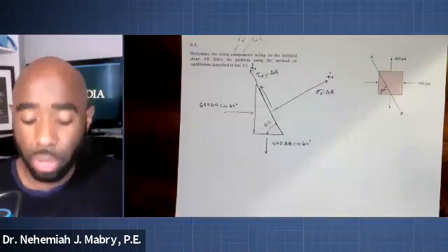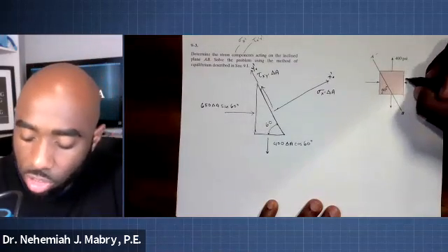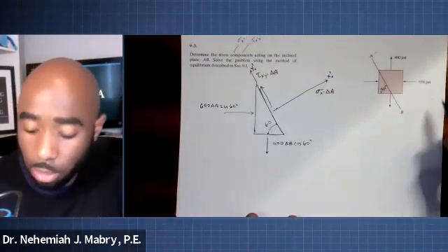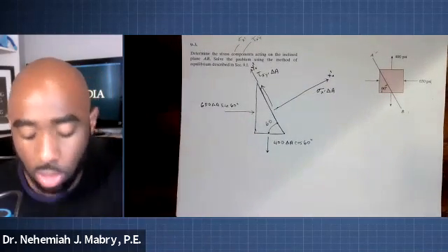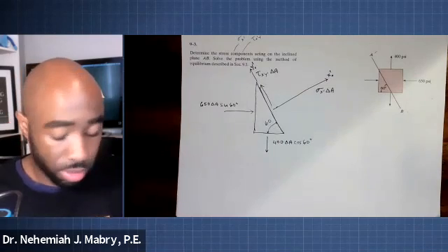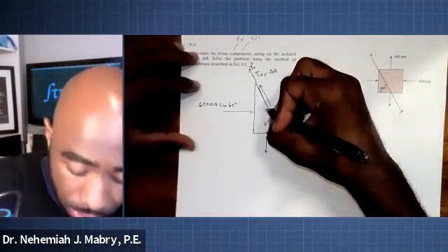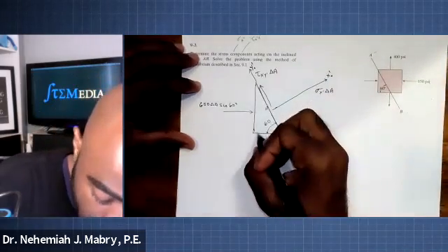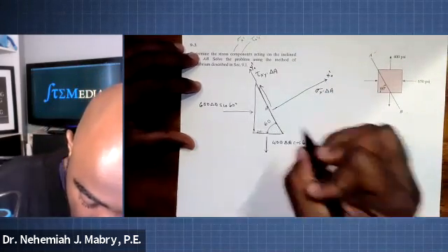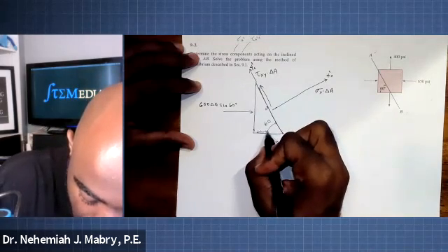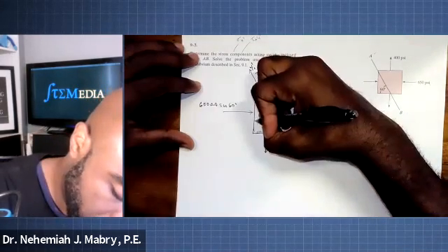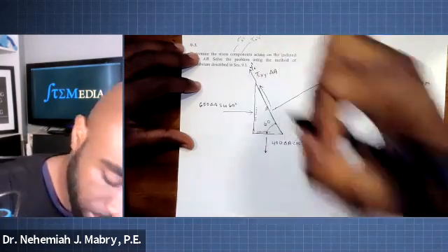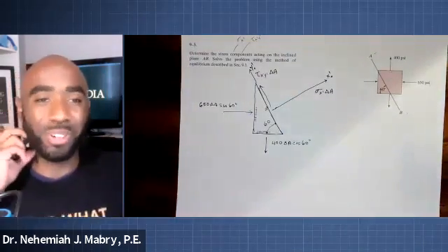And this is how we're going to do the method of equilibrium. Now, if we had some shear stress here, we obviously would need to draw shear stress like in our last one, but we only have normal stresses. So this is how we're going to draw our triangle in this case. Keep in mind again that this is the delta A face. This here is delta A times cosine. And then this side is delta A sine of 60, right? Let's not forget which surfaces are which.